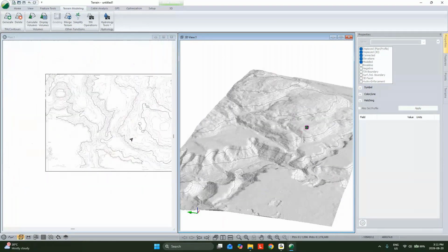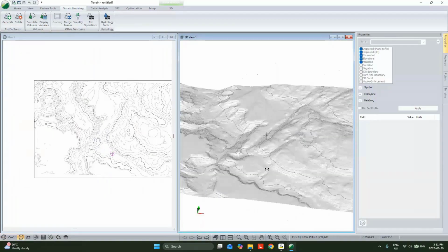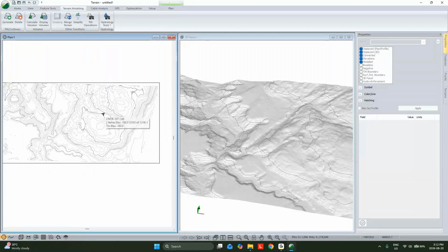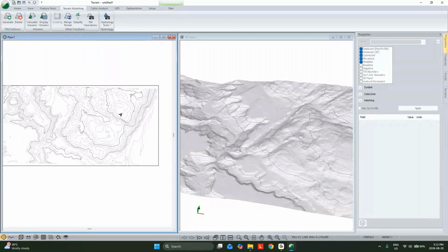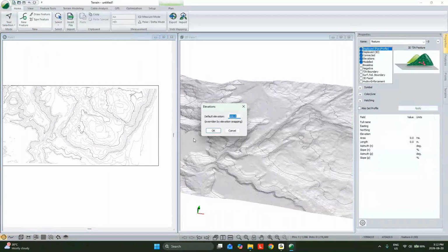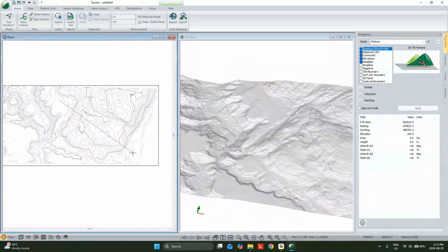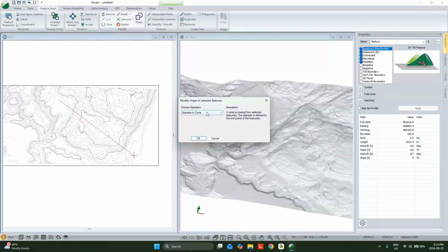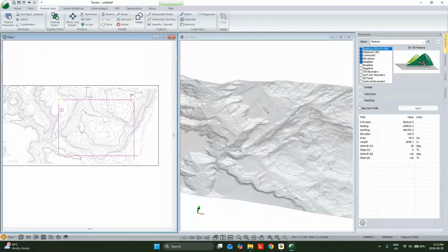And then the next thing that we're going to do here is we're going to assume that maybe we don't need all this area as high resolution. For that, I could just draw in a boundary feature, and I could do the whole thing drawing my edges in. Of course, it's sometimes nice to have nice regular features at the click of a button. So I'm going to take that diagonal I have drawn and turn it into a rectangle. This feature is tagged as the feature. I'm going to call it AOI, just so I can keep track of it.